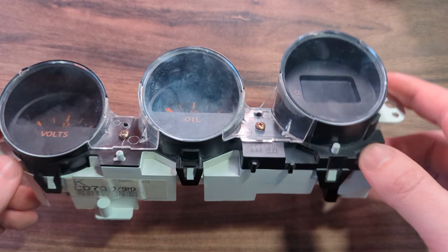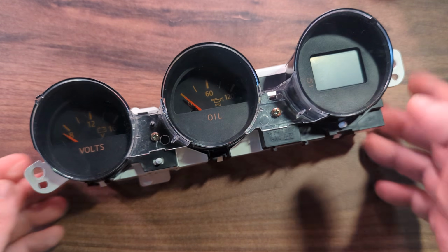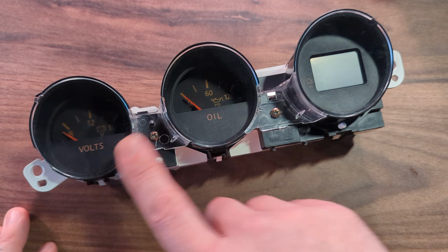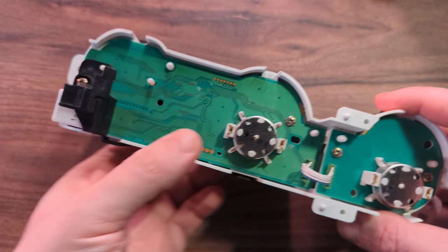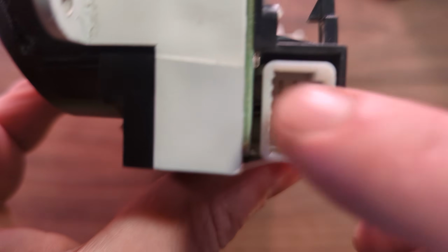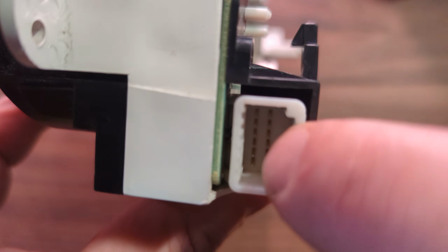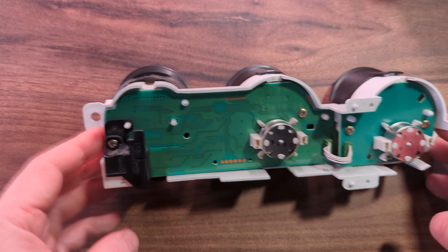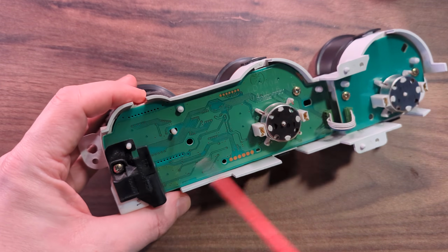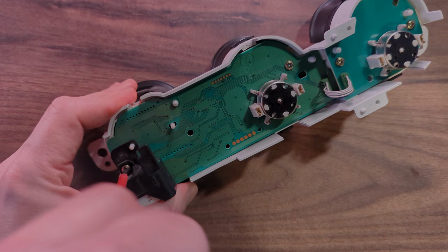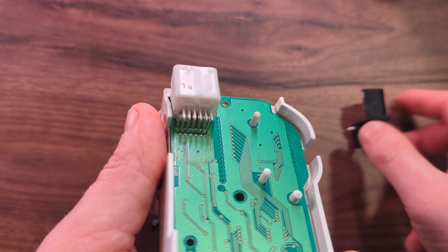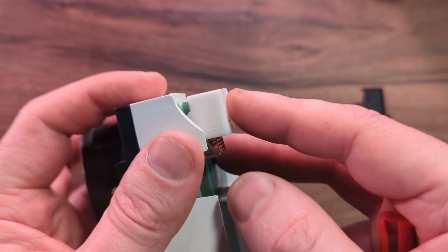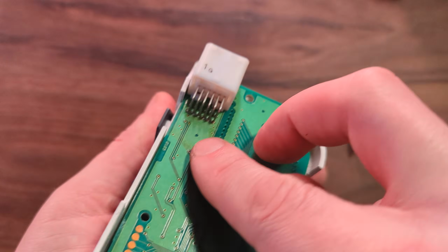This is the triple gauge meter that I've already removed from the car, and you see we've got the oil pressure in the middle, battery voltage, and then this multifunction display. Then there's a clip on this side. It's got 12 pins in it, and when we put that in, these receive different things. One of them is the oil pressure, one's the battery voltage, and there's a bunch of other stuff in there. So how we're going to do this is we're going to start by removing this. And it's the fact that we can access these on the back, which are just right angles, to take the pins and put them into the PCB.